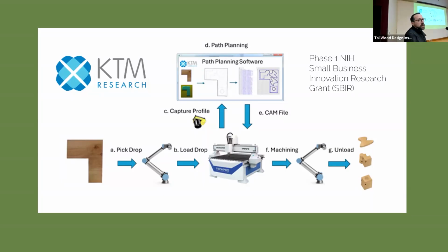What they're also helping us with is a nesting and optimization strategy. If we have our furniture product library with the individual part components, we can use the nesting software to optimize based on part rotation and kerfs and all that, so that random sized, random shaped scraps can be optimized towards that process.